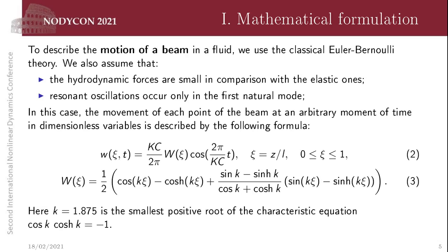To describe the motion of the beam in the fluid, we use the classical Euler-Bernoulli theory. We also assume that the hydrodynamic forces are small in comparison with the elastic ones, and that the resonant oscillations occur only in the first natural mode. In this case, the movement of each point of the beam at an arbitrary moment of time in dimensionless variables can be described by formulas 2 and 3.